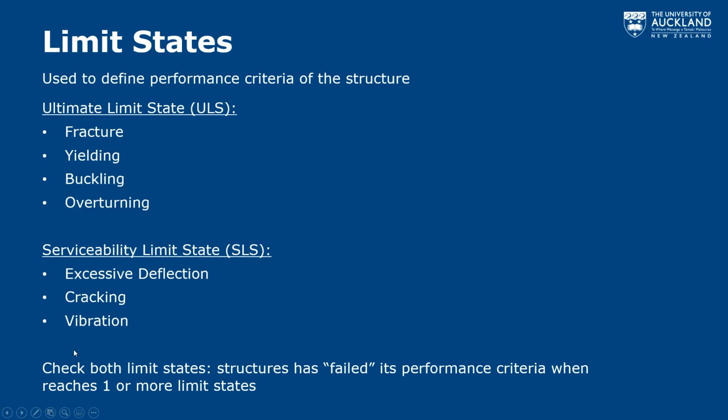As I said before, your floor might vibrate too much. And so, again, with all of these, if we, quote unquote, fail a serviceability limit state, well, the building's not performing as well as it could, but no one is in danger. While our ultimate limit state is really in order to make sure that we maintain safety of the structure, be it the building or bridge or any other type of structure we would be designing.